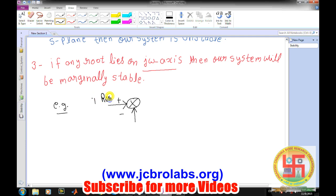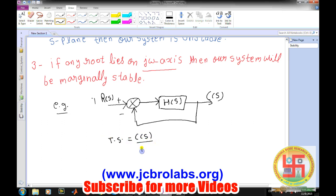This is, let's say, R of S input, and it is going into H of S, and this is the C of S, and we have this unity feedback system. So our system transfer function will be C(S) by R(S), as we know from the definition of the transfer function, output upon input, and this will be H(S) upon 1 plus H(S), right?